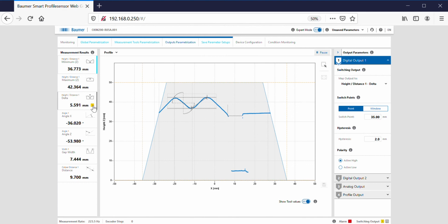You can see here, as soon as I clicked it, it puts the number 1 output next to it here in yellow, and I say, right, as soon as it's reached over 7 mil, then that means it's okay. And I can have it as active high or active low, so normally open, normally closed. And what's the hysteresis that I'm allowing on the measurement, that sort of thing.